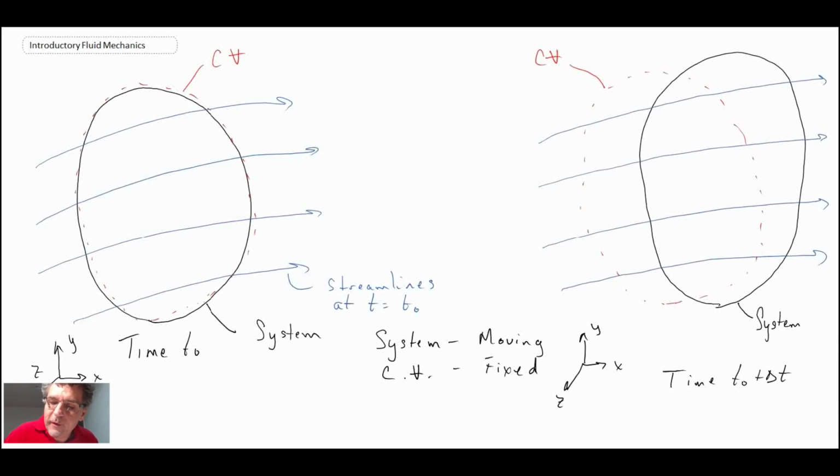Okay, so what we show here is the control volume, which, as I said, was fixed. It's not moving, but the system is. The system is occupying the fixed mass. And we're going to assume that there are three regions. The first region, region 1, is defined by the boundary between the control volume and the system. Then we'll have region 2, which is again bound by the system on the left and the control volume on the right.